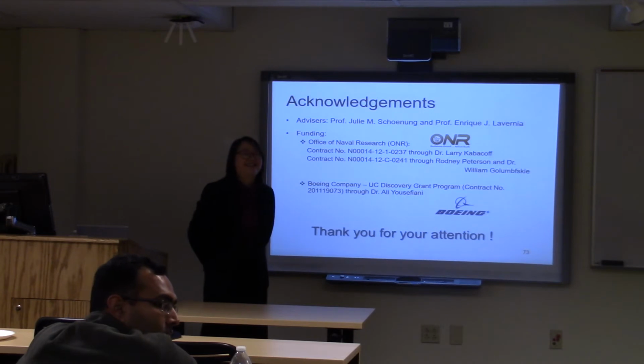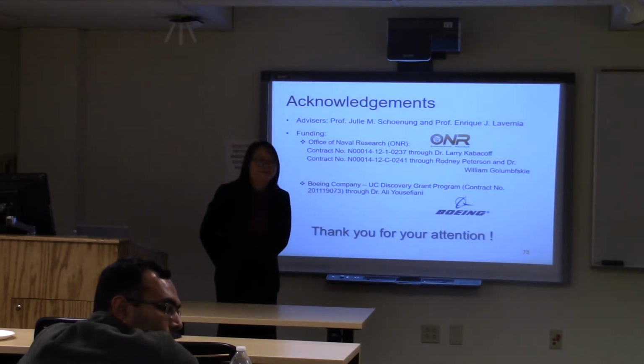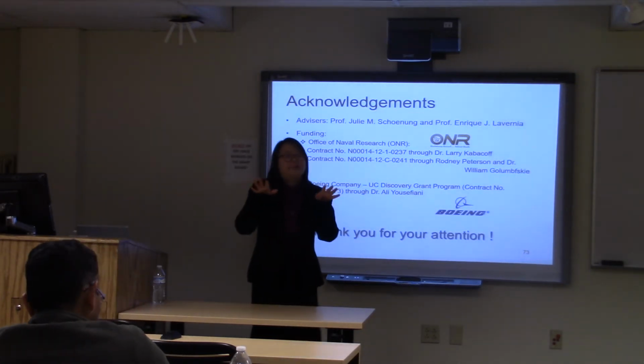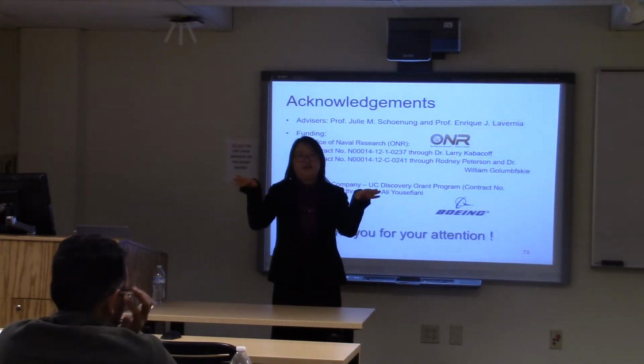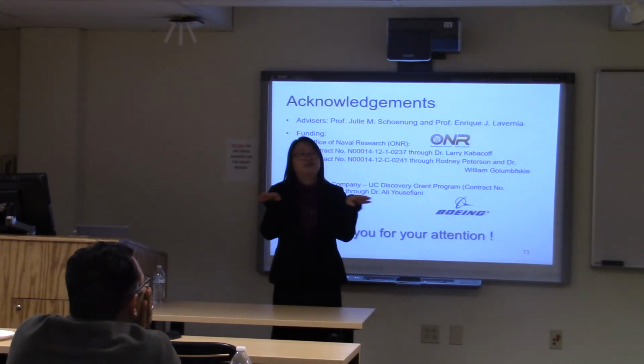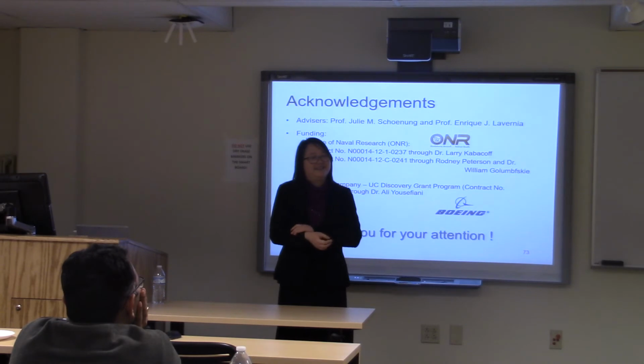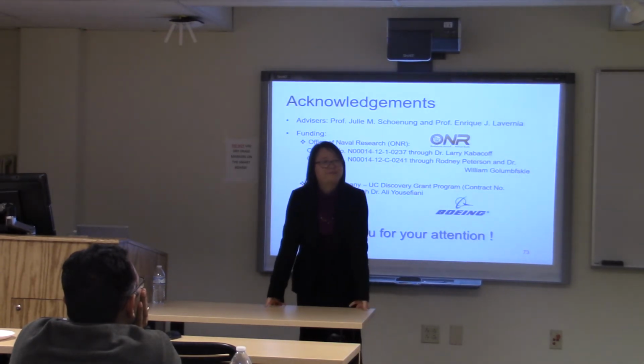Yes. Did you compare your T6 UFG to a T9 in the conventional grain size? I usually try to compare the coarse grain and ultrafine grain material in identical conditions. Right, but you've already cold worked essentially your ultrafine grain, so it would be interesting to see what the T9 condition properties of the CG look like.